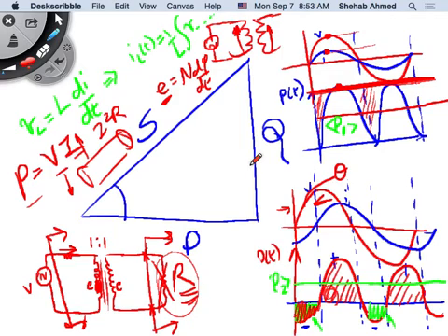I'm generating power using a machine, and transferring the power on cables. These cables are conductors with current flowing through them, meaning they have some equivalent inductance. I have transformers, which add additional equivalent inductance. So I have to feed that reactive power, to feed that load, which is consuming only real power.